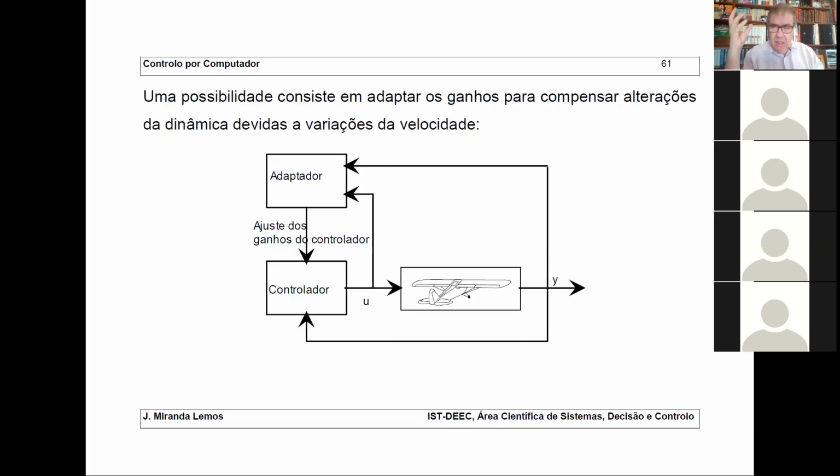The most basic one is PI, which has an interest by itself, but I also showed it to explain how we can write a very simple algorithm. Then I called your attention to the possibility of having more sophisticated algorithms, in particular gain scheduling, which is a very powerful idea, connected to patching controllers for different conditions of work, or adaptive control.